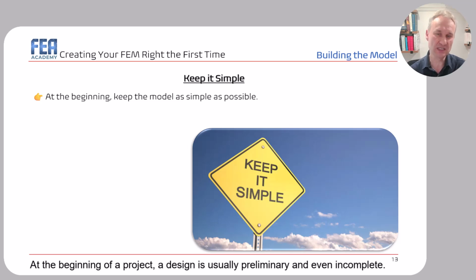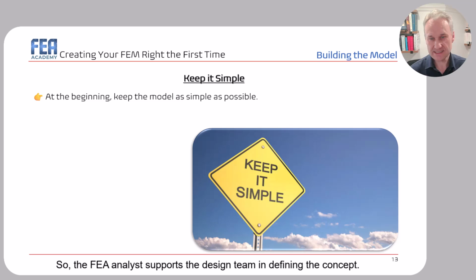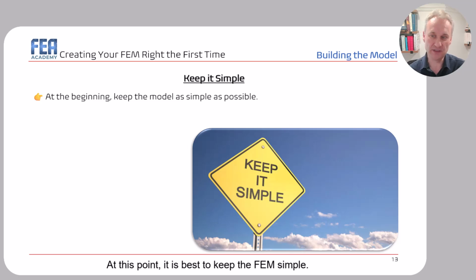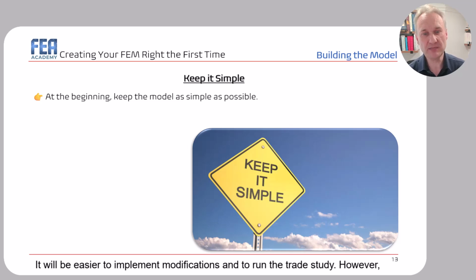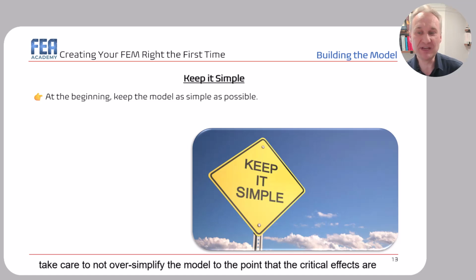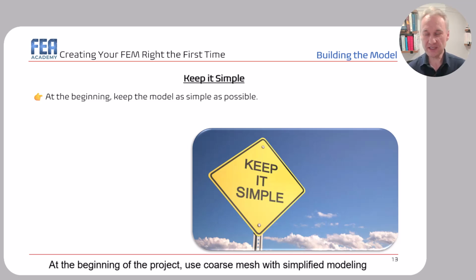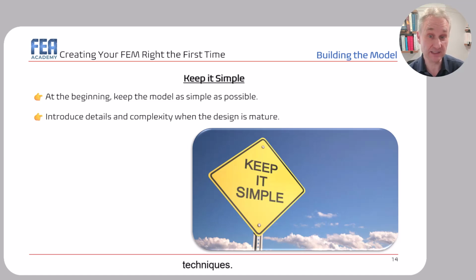At the beginning of a project, a design is usually preliminary and even incomplete. So, the FEA analyst supports the design team in defining the concept. At this point, it is best to keep the FEM simple. It will be easier to implement modifications and to run the trade study. However, take care to not oversimplify the model to the point that the critical effects are missed. At the beginning of the project, use coarse mesh with simplified modeling techniques.